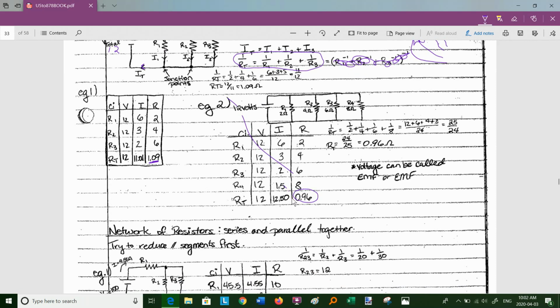And this is how we overload our circuits, how we blow a fuse in our circuit at home, which are wired in parallel. If you put in too many appliances, then your equivalent resistance, parallel equivalent resistance, sometimes written RP, is going to get smaller and smaller. And if it gets smaller, you're going to be drawing more current.